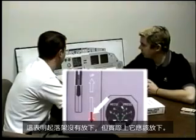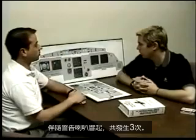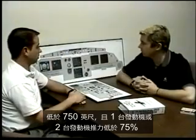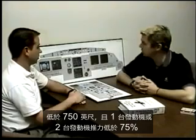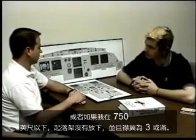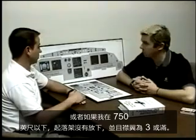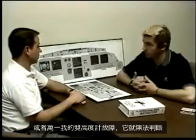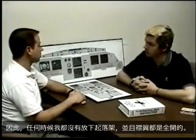This red down arrow on the landing gear panel, explain that to me. That indicates that the gear is not down, and it should be. It's accompanied by a warning horn, and it occurs 3 times. Below 750 feet, and the thrust is below 75% on one of 2 engines, or below 97% on 1 engine. Or if I'm below 750 feet, gear's not down, and the flaps are 3 or full. Or in the event I have a dual altimeter failure, it can't tell what altitude I'm at, so anytime I don't have the gear down and the flaps are at full.